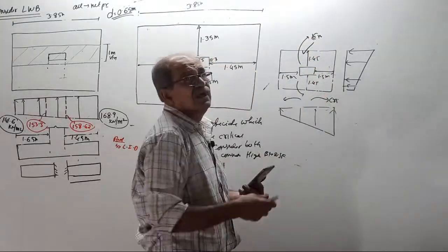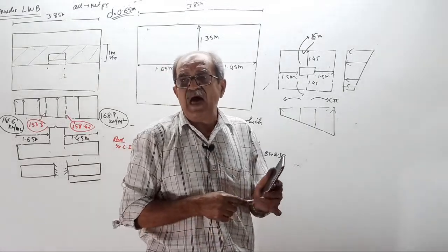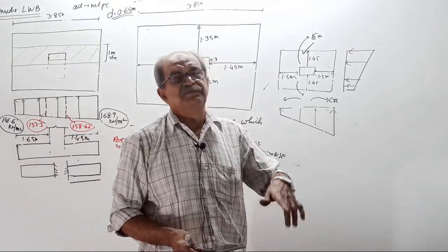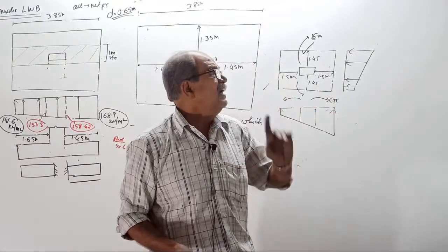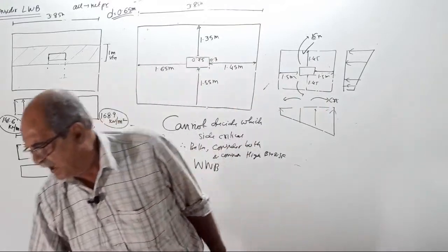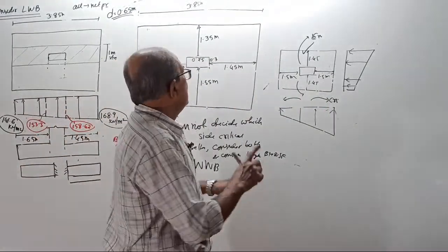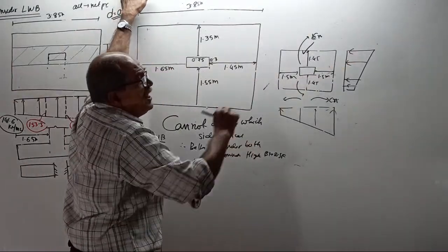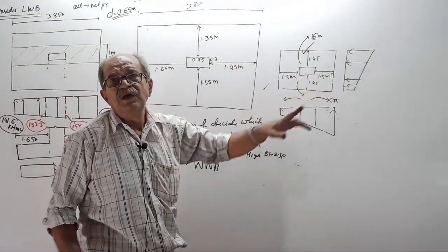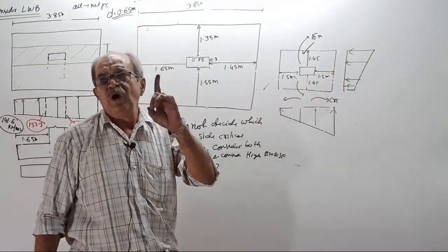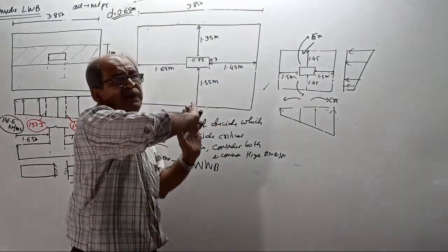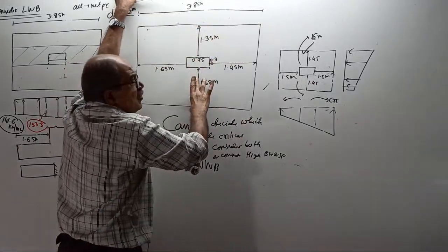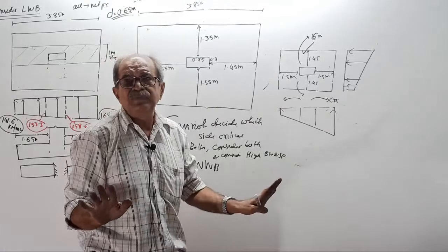Over. So, when I take up my example later, when I do a problem, a column subjected to so and so, when you get the pressure, I will just tell in the class, remember: lengthwise bending, both are equal projection, but see the loading, that side has more pressure, so you consider for lengthwise bending the right side part. And when you take widthwise bending, see the projections are equal, so projection does not matter, both are equal.